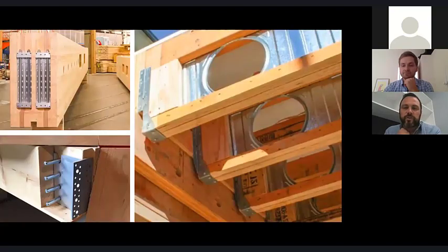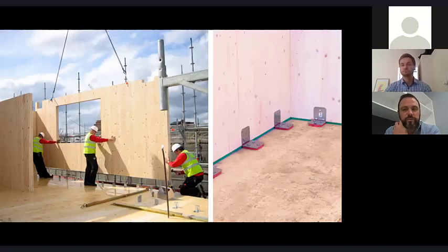Yeah, and just to add to, we'll probably touch on acoustics a bit later as well, but there's this perception in the market that you need all these rubber strips, and I'm not saying you don't, but most of 55 South Bank didn't have any, and we had a really strict acoustic requirement, and we did on-site testing, and we worked with some really good acoustic engineers, and it passed significantly well. So, looking at those rubbers, it's important to investigate because they are very expensive, and it's a very European approach that they've gone and said, look, it's needed, and it's something that should really be challenged during the design process.